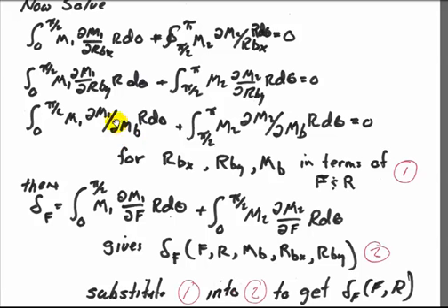to that moment, MB. This set of terms will give us the slope deflection, or the slope of the beam at the place where that moment is applied. But we know the slope at the cantilevered end is 0, so we set it equal to 0. And then we do all of the integration, which again is going to be big, ugly, and tedious. Okay, but we do that integration and we solve for MB out of this equation.